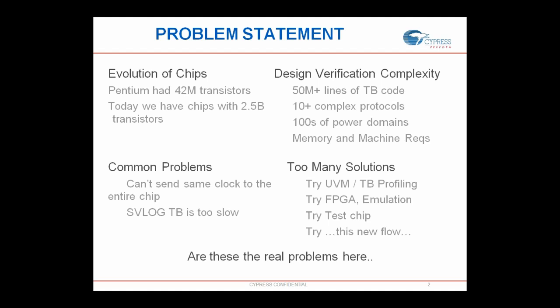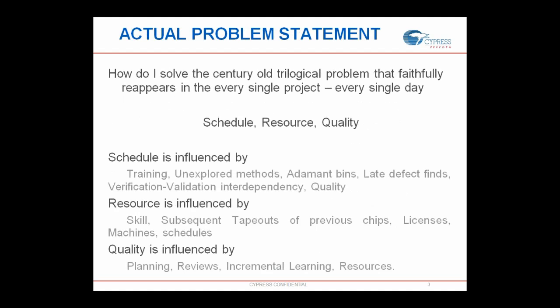Unexplored methods. There could be lots of problems while writing testbenches, in SystemVerilog, that could cause trouble to the schedule. Your coverage model could have extremely adamant bins which cannot be hit at all, even though you have the superpowers of randomization. For those, a directed test or other alternative methods need to be deployed to solve that.